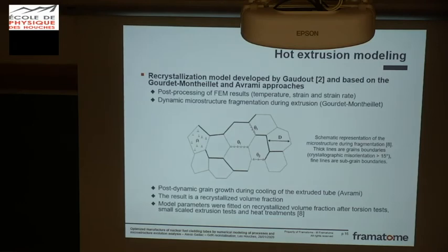And in the last years, we included in the finite element model of extrusion a dynamic recrystallization model developed initially by Gourdet-Montheillet and adapted to zirconium by Benoît Godou. So it includes the dynamic recrystallization model during deformation, but also a post-dynamic recrystallization after extrusion. For this, we post-process the finite element model results, mainly the temperature, strain, and strain rate during extrusion.